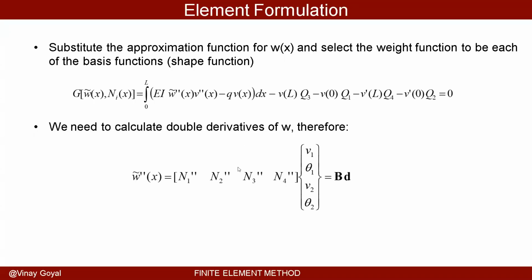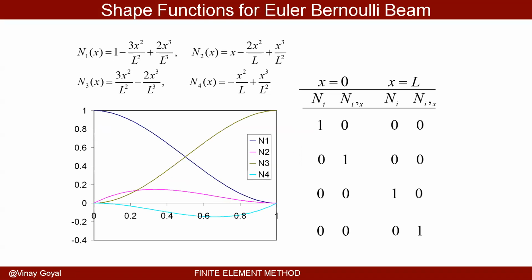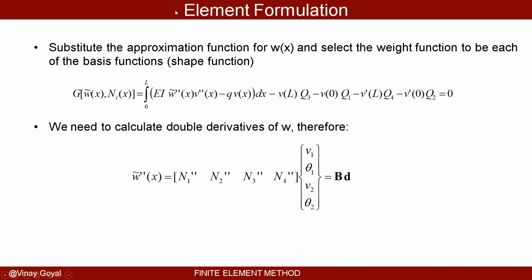And so now I'm ready. I'm ready to do some damage. How do I do that? I have this deflection, which I know how to approximate now using these shape functions, N bold times D bold. Now the idea is to just plug that into the weak form. And we already learned how to do that.